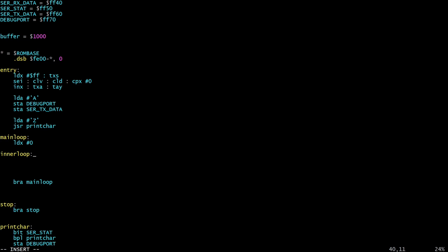So we're going to call print char after read char, and if the character was a line feed, then a whole line of input has been entered, and what I want to do in that case is print a couple of blank lines and then print back the entire line that the user typed. So we should end up with a kind of double echo thing. You're going to type a line of text and hit enter, and then the 6502 computer will send the entire line back again, and the user will see a copy of what they typed.